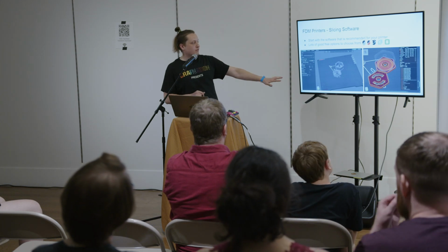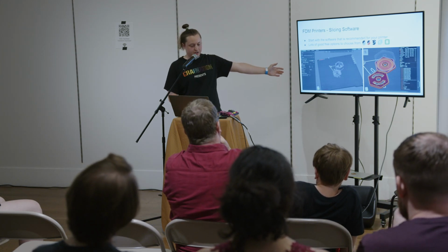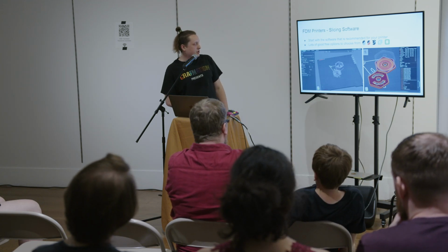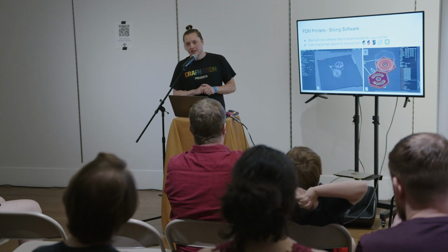This is kind of the general layout of most slicers. So this part is pre-slicing. You have some settings for which printer, types of filament, and then some general print settings. There's an easy and an advanced mode. I generally say start with the easy one. Most of the time, anything that's in the advanced settings, you don't need to change very much. So anything that you would generally change, like the layer height, you would just do in the easy settings, and that's mostly what you would change.